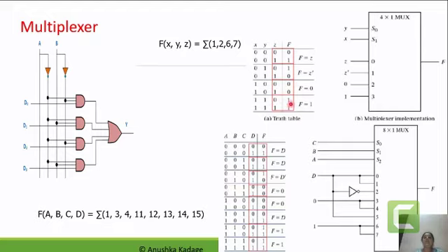Similarly, for the remaining two min terms also, either f equal to z or f equal to z dash is not true for both of the input combinations. And that's why here we are going to mention f equal to 1. And we are making the combination of two min terms' corresponding outputs because we are restricted to only 4 input lines.